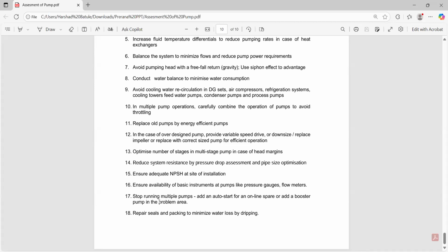You can save much power in that particular application. Or if you have multiple pumps running and your water flow requirements are variable, you can add on-off control to that system with flow feedback of the actual requirement.